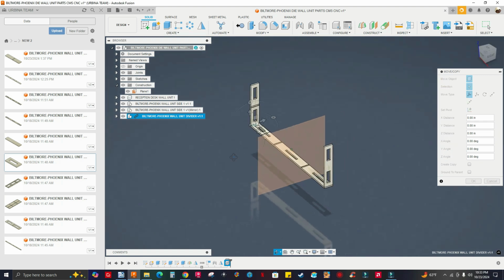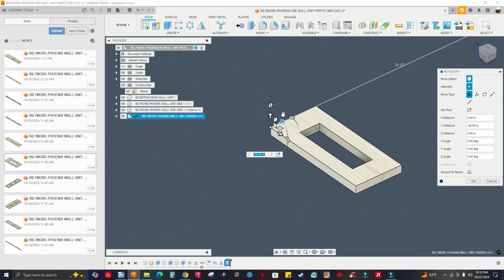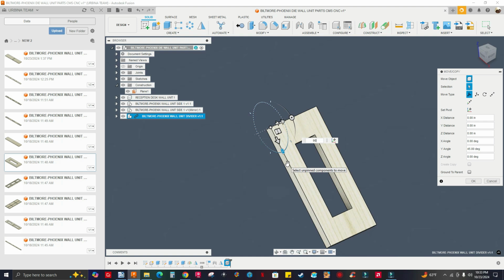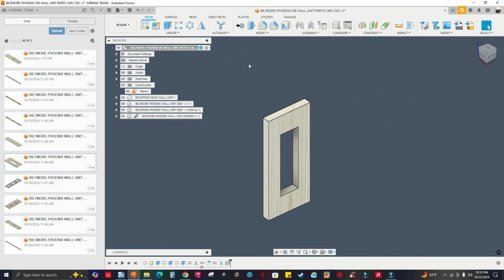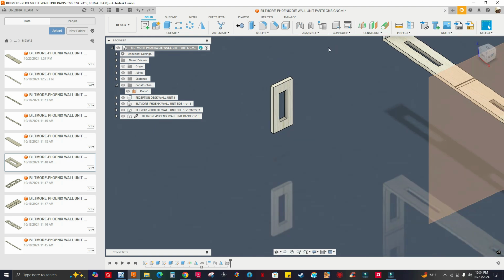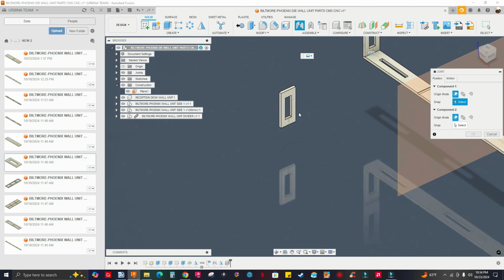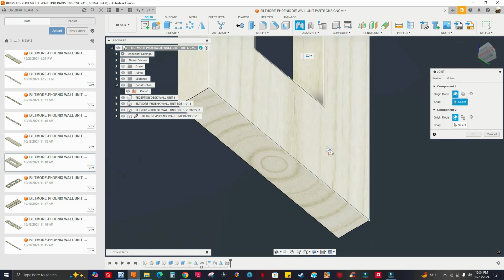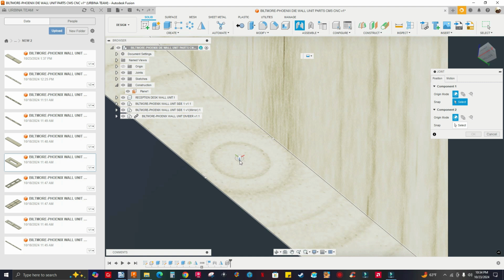And I'm gonna have to rotate the model, so I'm gonna drag it here and grab this wheel right here, rotate. I'm gonna type 90. Click OK. I'm gonna select joint, which I do see it here. So joint. If you don't see the feature, you're gonna have to close or hide the data panel. So joint, rotate. I'm gonna hold down Control key, snap it right there to the midpoint.